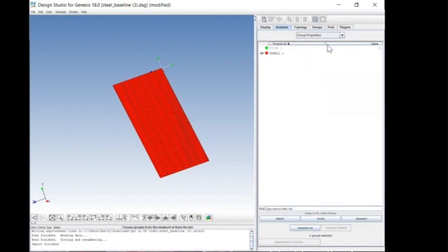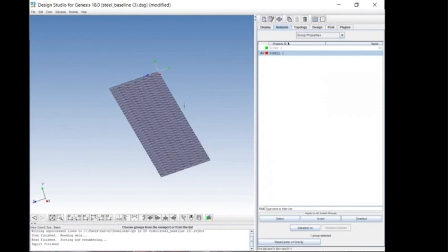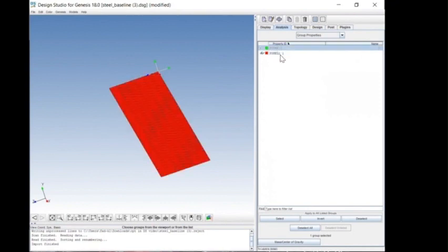So if we click on finish, we've now got our red physical property, which these elements are still pointing to. We can see that. If we click on that red physical property, all these elements are highlighted. This green one, which we've just defined, this P-comp, that's grayed out actually because there's no elements in that physical property.